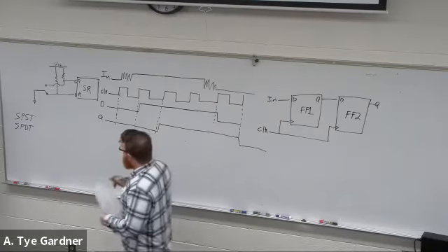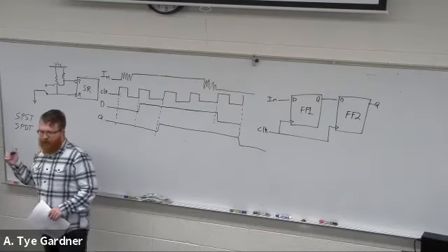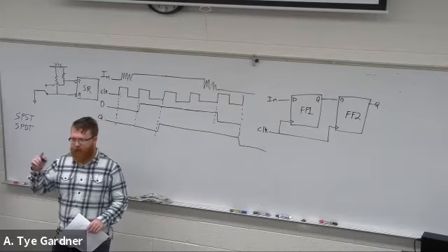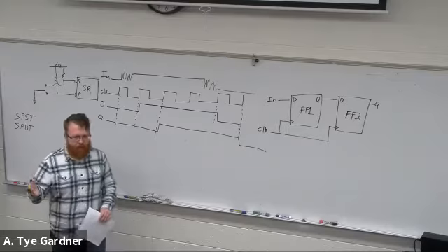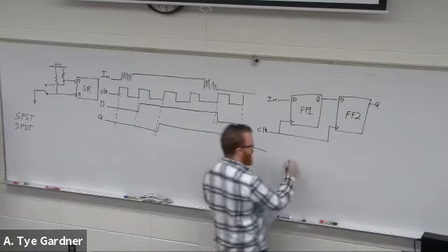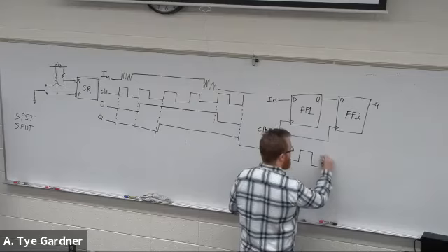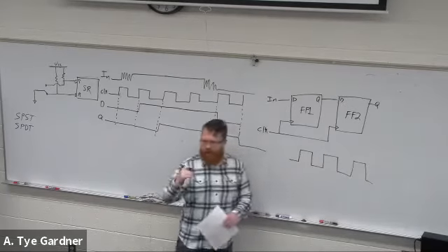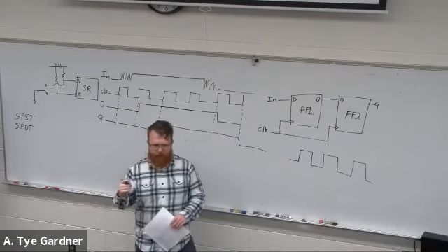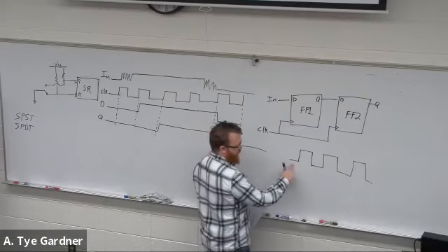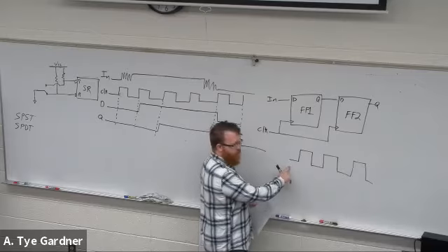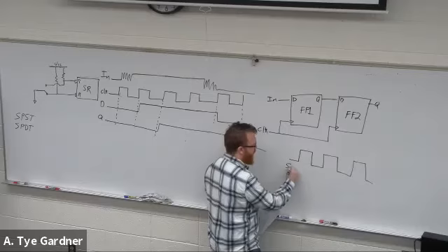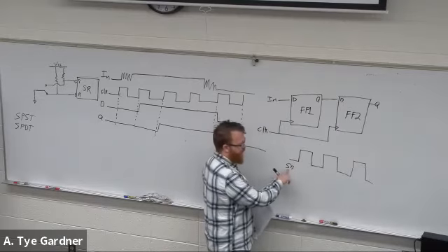Now, what I've had you do in the past is use your state machine. You can use the state machine transition to update your ready signal. So for example, let me do just a couple of clock cycles here to illustrate the issue. So I want to assert the ready signal for my UART. Well, let's say before this clock, I'm sitting in, what do we call it, the stop bit state.